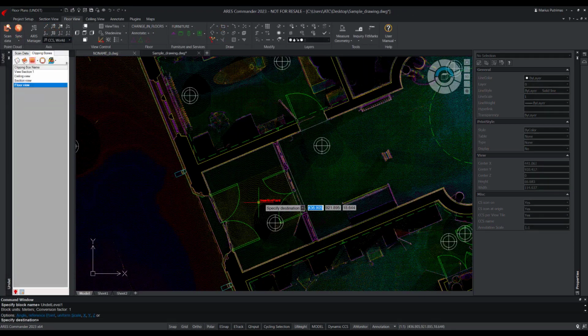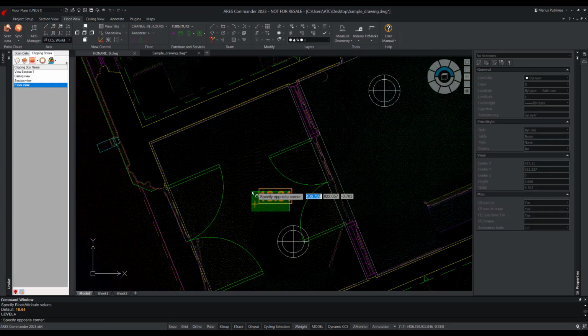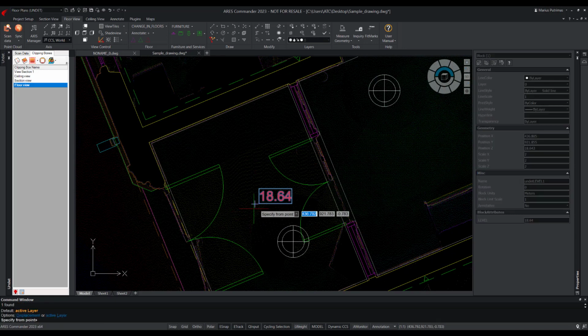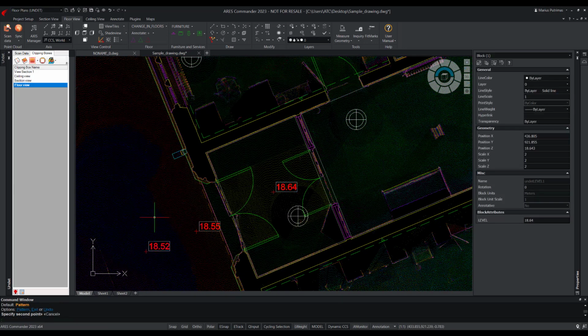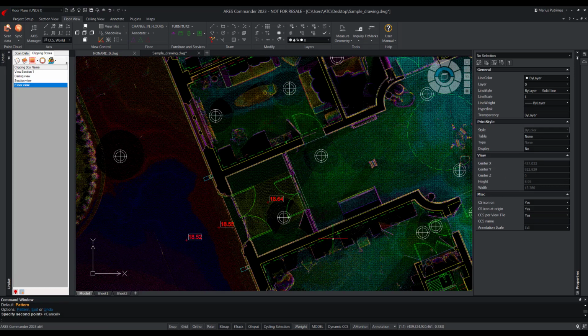So, the first annotation method is to use blocks with attribute values. When snapping such blocks to point cloud points, the level of a particular point cloud point is recorded as an attribute.